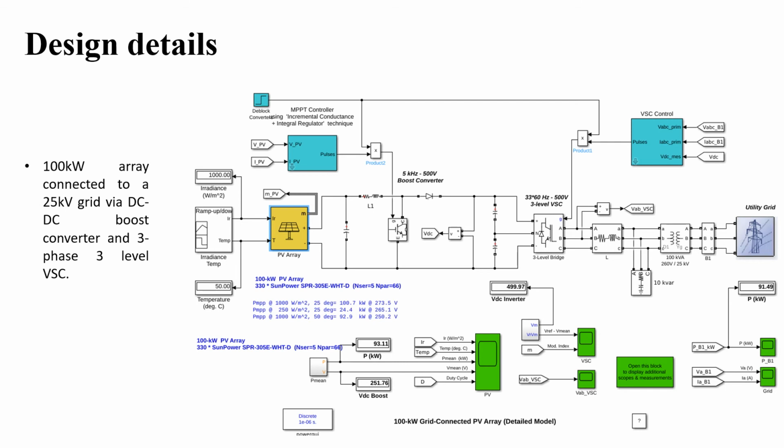Referring to the PV array block, we can directly control the number of strings that are connected to the photovoltaic power generation modules. We can also control the maximum power level, open circuit voltage level, open circuit current level at the maximum power point, irradiance level, and the operating temperature from the PV array block. We can also select the commercial PV array from the library itself. For this simulation, we have considered a SunPower SPR 305E type module, which is widely available in Canada.